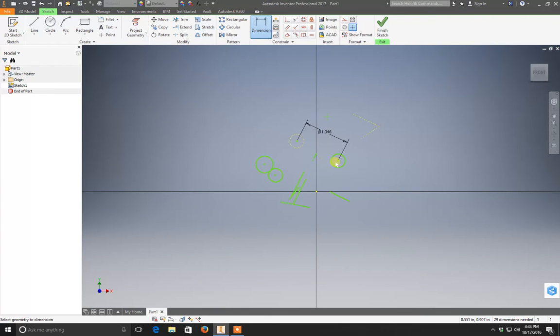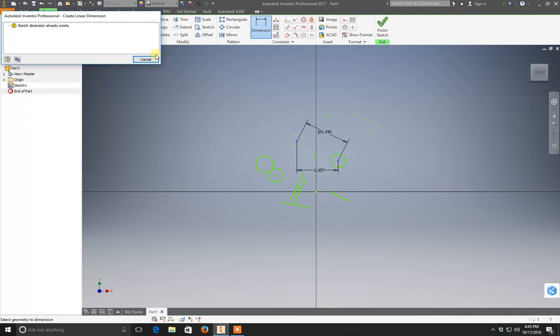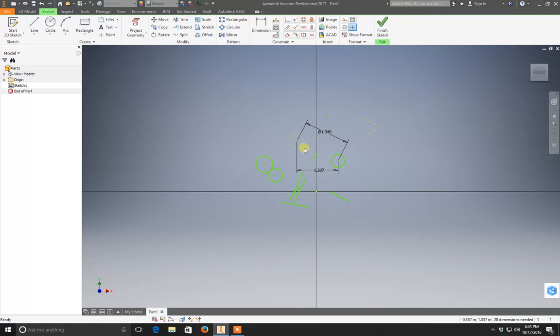And then a driven dimension, I'd say, okay, let's find the distance between, if I just say between these 2 points again, it's going to let me do that. And again, I didn't demonstrate that, but basically it's saying, okay, you've already shown this dimension, so now this dimension, we're going to show you what the dimension is, but you can't actually edit that dimension.